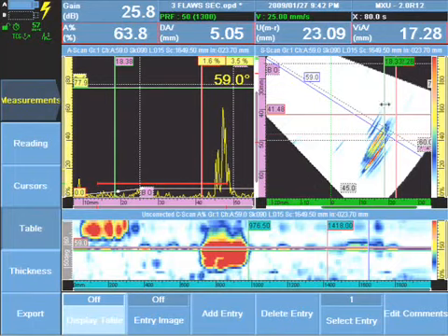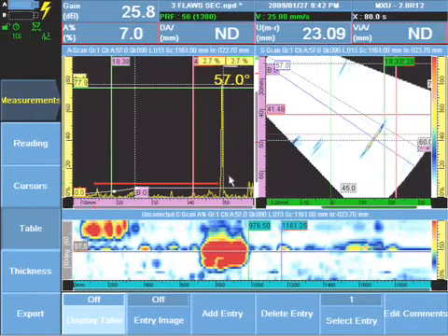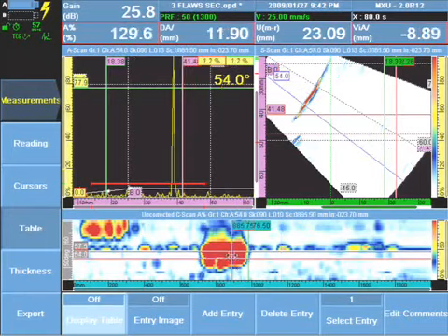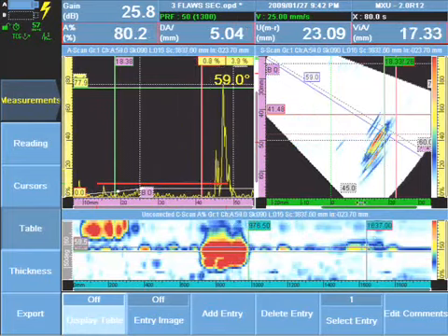Notice the difference between the signal in the S-scan and the A-scan of cap geometry, of a linear indication such as sidewall lack of fusion, and of an indication of a crack. All the tips and facets of the crack are generating small tip diffracted signals.